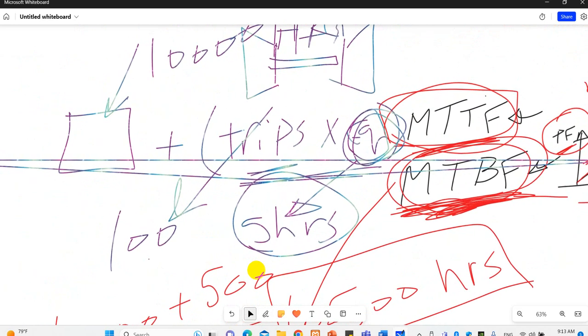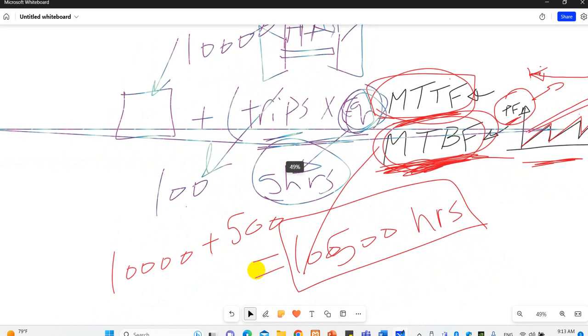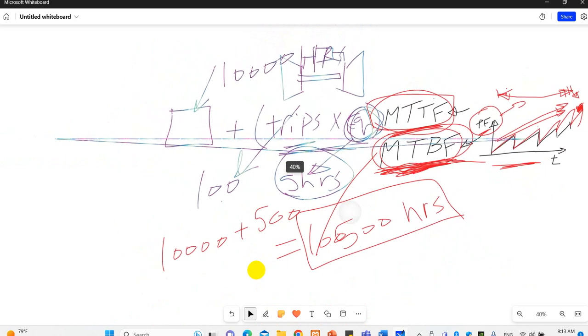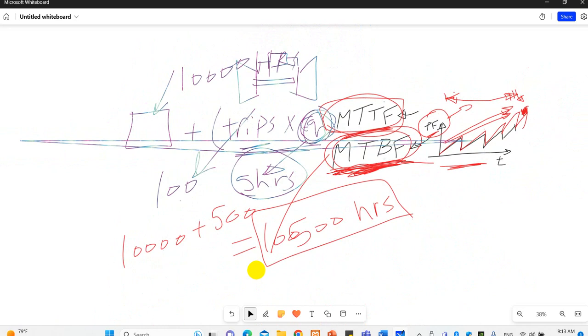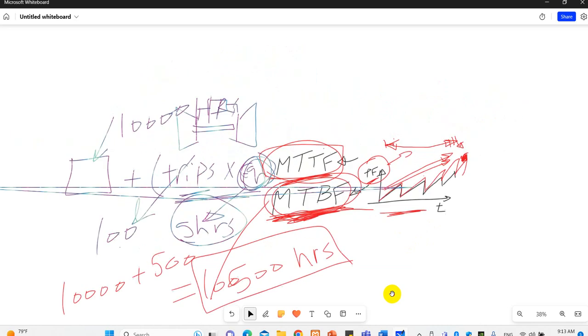Okay. Why that? Because he takes into consideration the stresses the machine is exposed to when you trip or start the machine, and translates these stresses into running hours. Then he gives you this guidance to decide exactly when you need to make your overhaul.